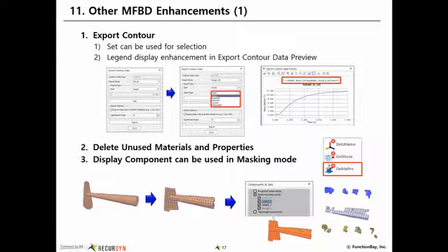If you uncheck one, all of the elements of that type will be masked in the model so you won't be able to see them anymore. That's fairly useful, especially since for RecurDyn to mesh, it had to include some different types of elements, so you can see if something was a little off, and if there are certain regions where certain elements just aren't looking quite right. If it had to use another element, perhaps that's a region of concern for your mesh having poor quality.